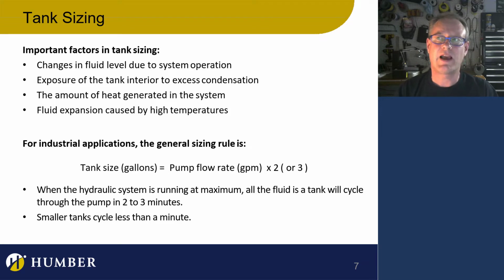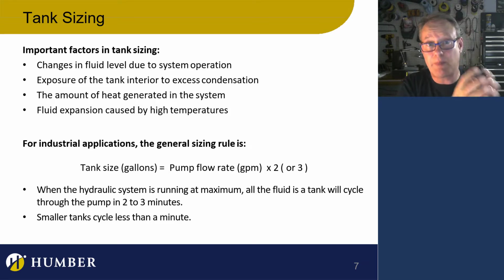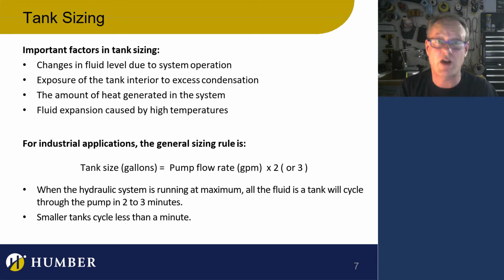Smaller tanks, I think you know this, but I'll tell you anyway: a power steering pump is just a hydraulic pump. I've seen applications where people have taken power steering pumps out of vehicles and used them as hydraulic pumps to drive hydraulic actuators. But the tank there is very, very small, just a tiny little thing. The steering mechanism doesn't use a lot of oil, but that fluid is circulating quite a bit.